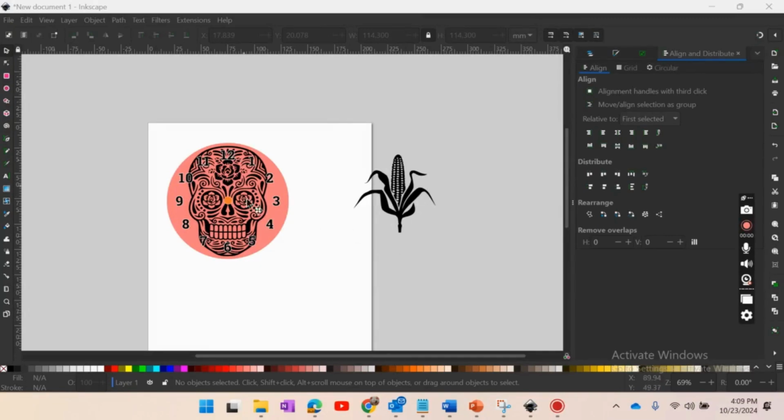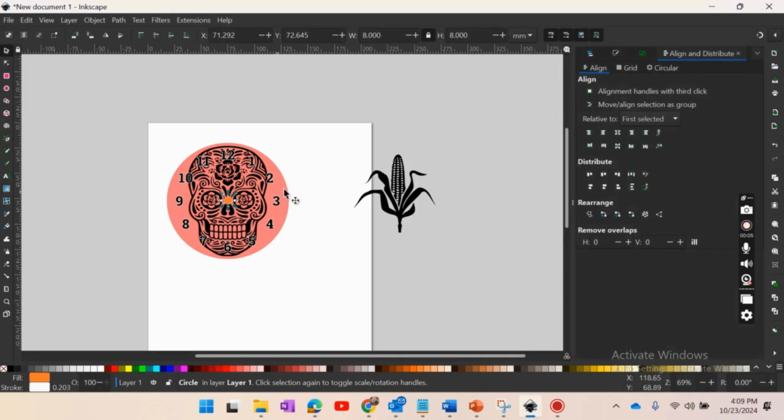So I've got all the numbers arranged on here, and you can see in the program that I am clicking on my center circle and I am clicking on my outer circle. And this is our last step, because if we don't have the final steps laid out like this, what's going to happen is, one, the laser is not going to do cut lines, and additionally, and most importantly, it might actually cut every single part of your clock out and actually damage it and make it not be usable. So for the sake of not wasting materials in the STEM lab and in general, we are going to make sure this is our very last step.